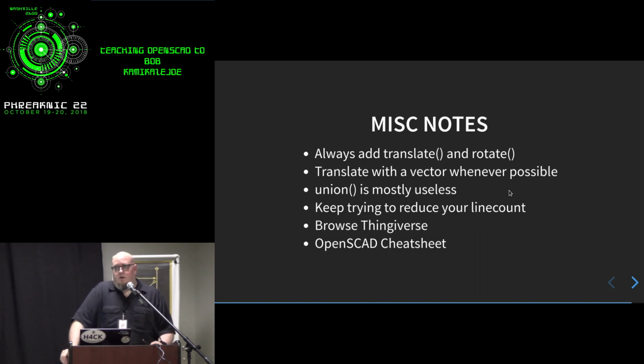I needed a hexagonal grid function for a project. I basically make honeycombs, and I found one that did the job on Thingiverse. It was kind of neat because I opened it up and he had like 10, 20 lines of code: here's how you do it, with all the proper geometry and math to figure out the angles for hexagons and spacing and everything like that. And he had that all commented out, and in a comment that said, here's the easy way. He took a cylinder and said it can only have 6 polygons. You have a cylinder, cut it down to 6 polygons, and you've got an instant hexagon. I was like, well, that's pretty genius.